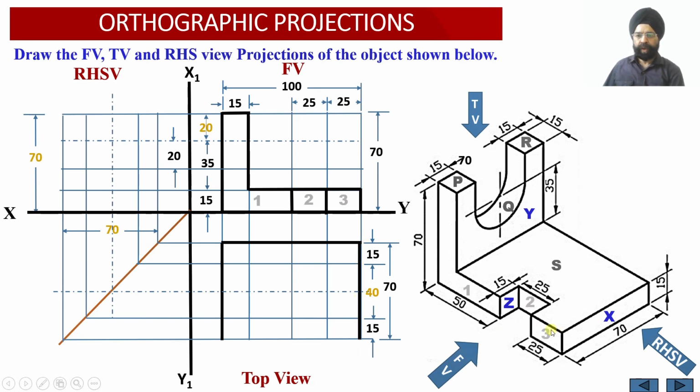And now I have to obtain the top view of this front edge. So from the front side, the observer will be checking that you need to move 25 millimeter towards the left, and then there is a rectangular slot which is measuring 15 millimeter depth and 25 millimeter width over there. So that now I can move 25 millimeter back. Now you have the depth equal to 15 millimeter, and then the width of the slot is equal to 25 millimeter once again.